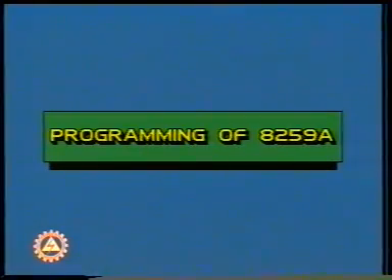The systems with moderate complexity do not need a large number of interrupts to be provided for the devices. In that case, the controller chip used as a single chip is good enough. But in the complex systems, of course, the cascading in the master-slave configuration has to be carried out. Now, let us see the programming of the interrupt controller 8259A. This needs initialization command words to initialize the controller.